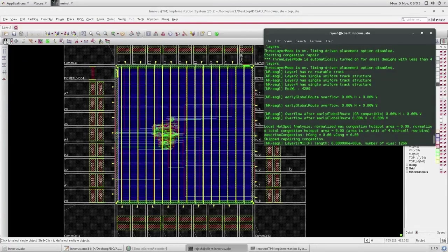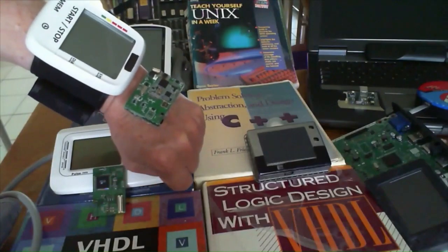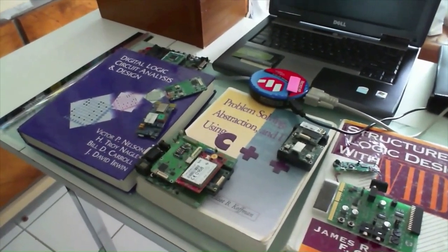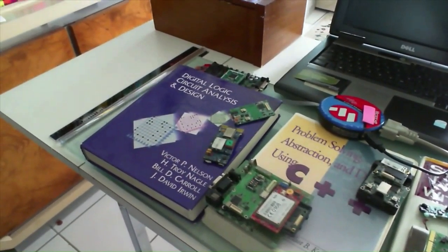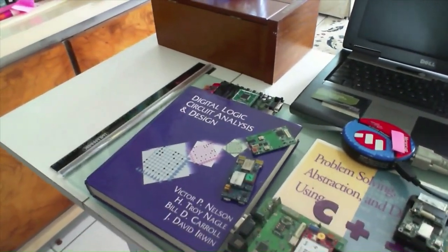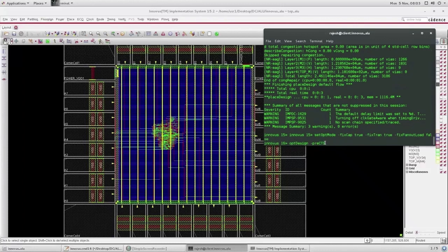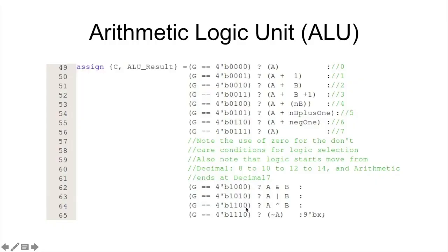It is important to ensure that the quality of the placement is maintained, such as clock skew, timing, and wireability. For instance, the smallest clock skew is achieved by preventing the circuits in timing critical clock trees from moving during overlap removal.